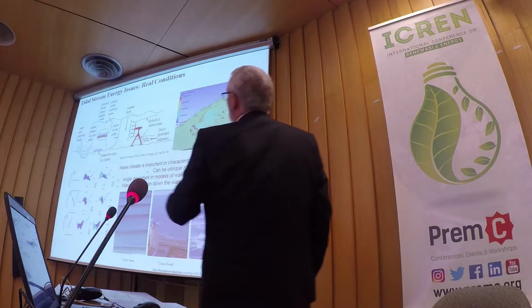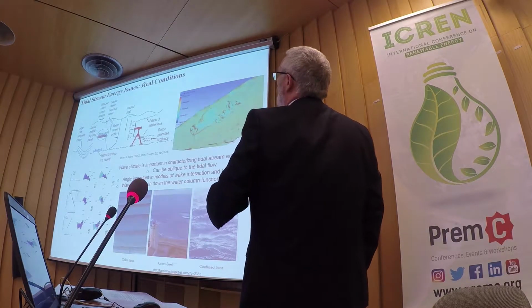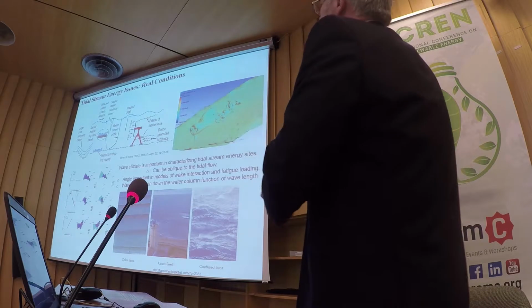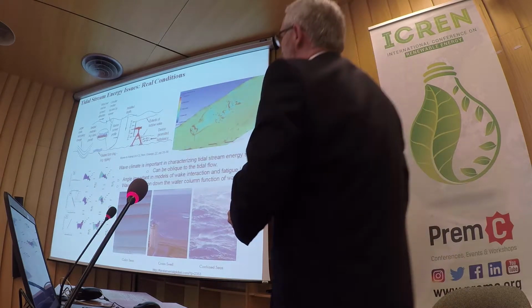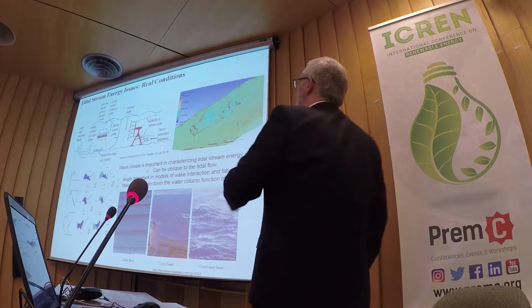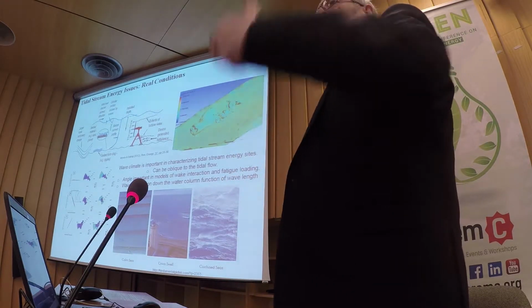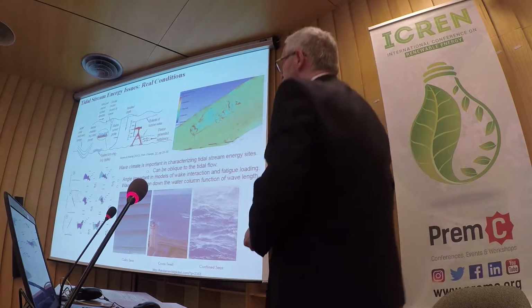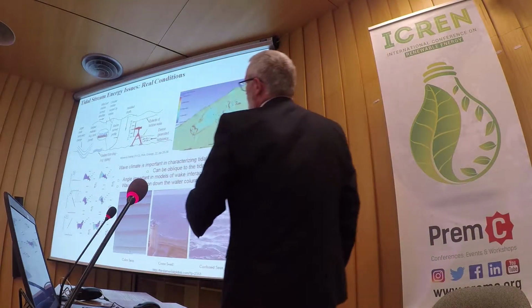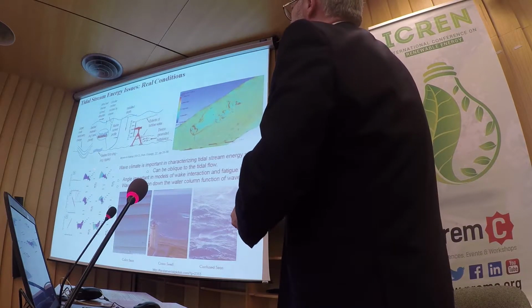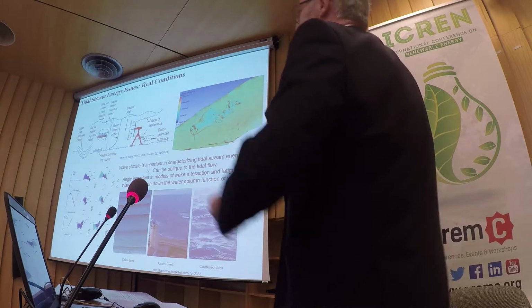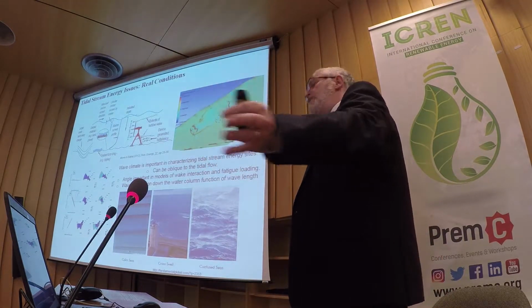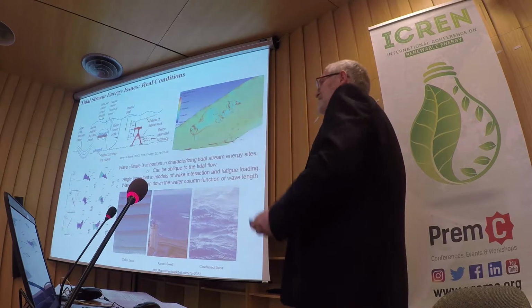In addition to that, you have this problem with wave penetration. Then you have the wake coming off all of the structure, and in fact this rotating body. So you end up with a scenario, all of that combined together, and you're going to have a bit of a messy flow that a turbine can be seeing. These tidal roses just show the various angles that you can actually get from different directions. So you can put a turbine in, and throughout the whole tidal cycle, you can actually get variations in the direction that are hitting it.